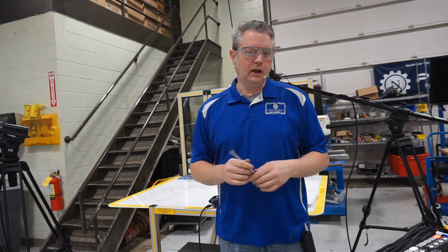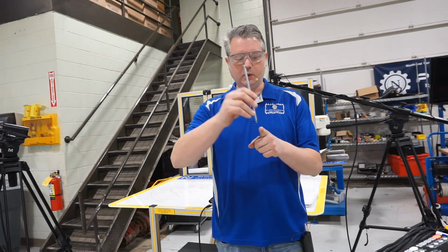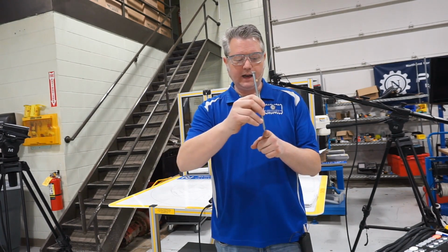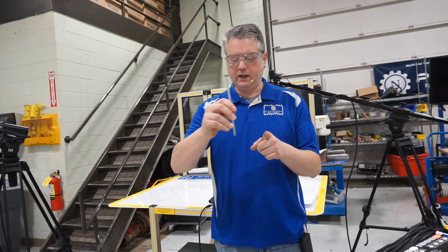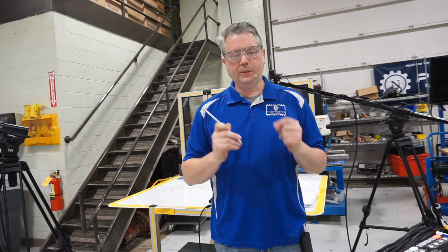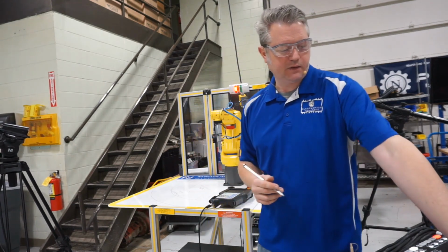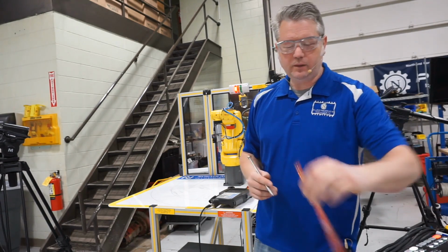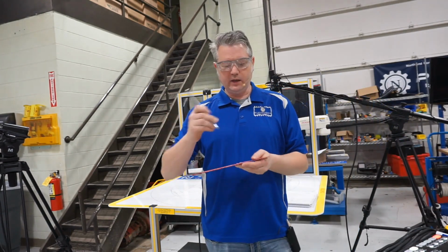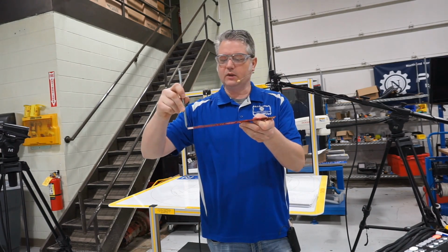The other one that's out there is called linear, or L. A linear move, when we have one point and another point, will actually move in a straight line from one point to the next. So that would be great. Let's say that we're doing welding on the seam of something, and it wouldn't be good to have a joint move if we're trying to get from this corner to this corner.